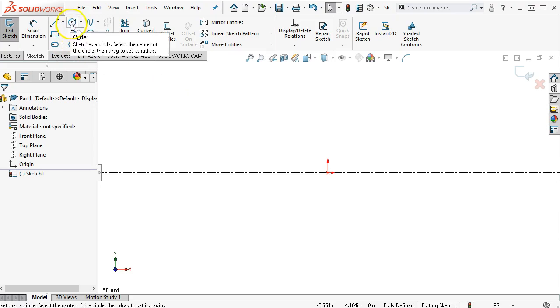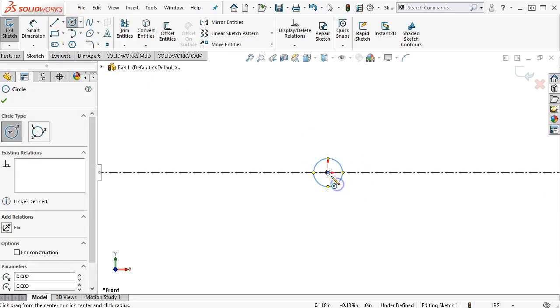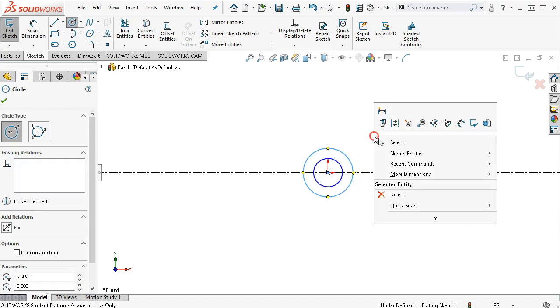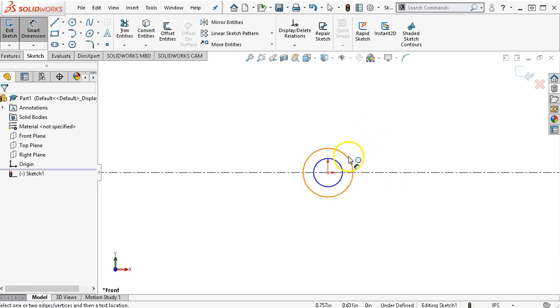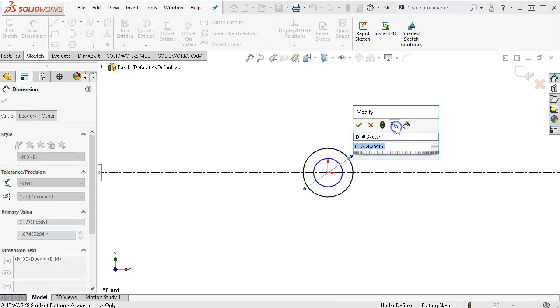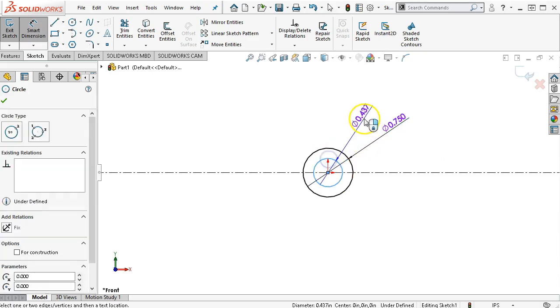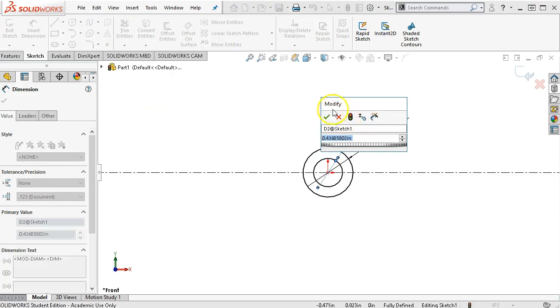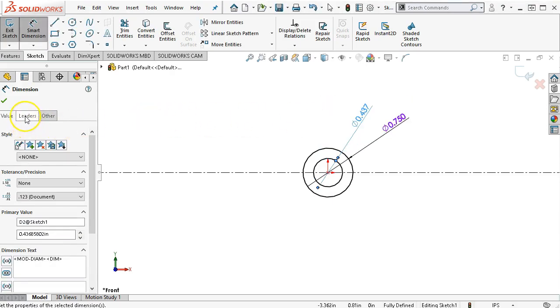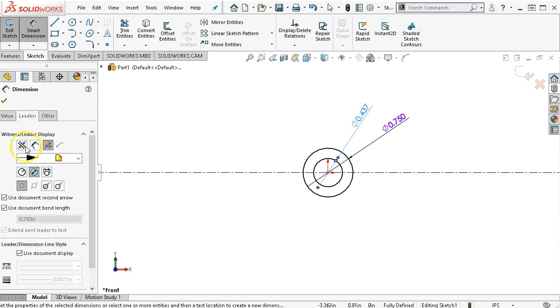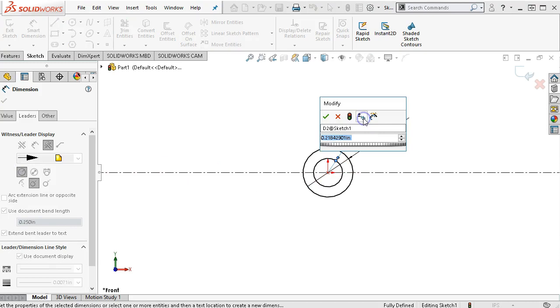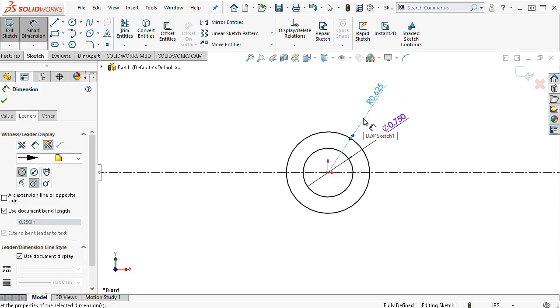We'll just start from the end. I'm going to use contours and regions to speed up a little bit here. So the diameter of the interior is 0.75, and the exterior is 0.625. Or no, that's given as a radius. So since that's given as a radius, we're going to switch over to the radius, and then we can go 0.625.